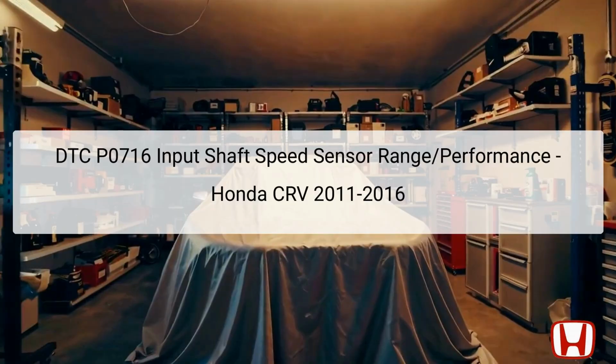The DTC P0716 indicates an issue with the input shaft speed sensor, specifically relating to its range and performance. This sensor, located within the transmission system, plays a crucial role in measuring the rotational speed of the main shaft, which is integral for the automatic transmission's functioning. An accurate reading from this sensor aids the engine control unit, ECU, in making precise gear shifting decisions, ensuring optimal performance and fuel efficiency. The DTC arises primarily from electrical circuit issues rather than mechanical failures in the transmission system.